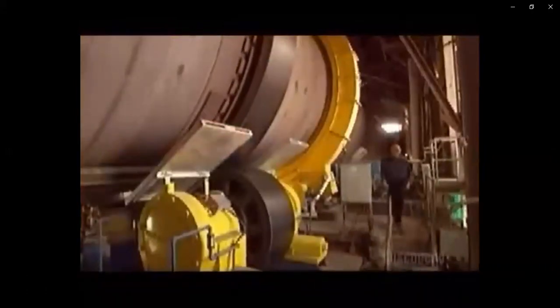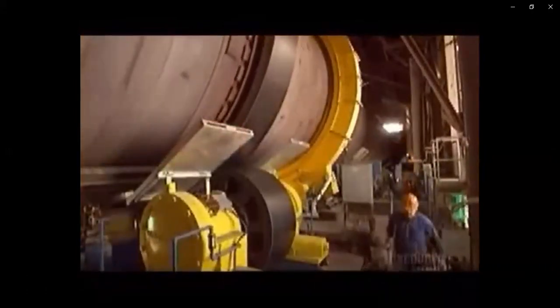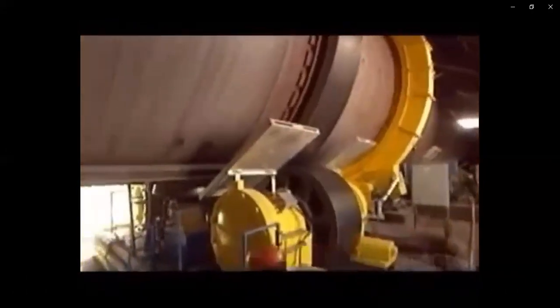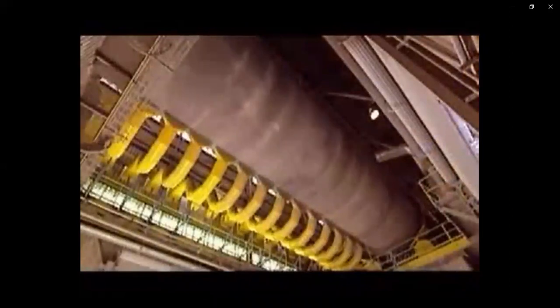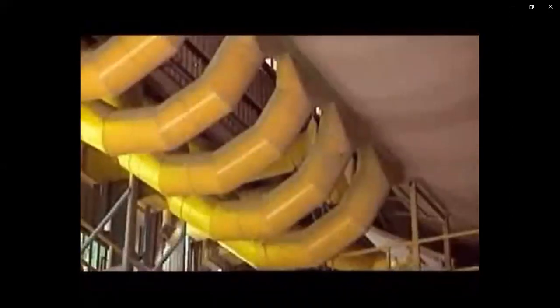The preheater is equipped with what's called a flash calciner. In about 5 seconds, it removes 95% of the carbon dioxide in the powder through a chemical reaction. This isolates the lime, which is the most important element in cement. From there, the powder moves into a rotary kiln, a huge cylindrical furnace. It's set at an angle so that the powder moves from top to bottom a distance of 49 meters.